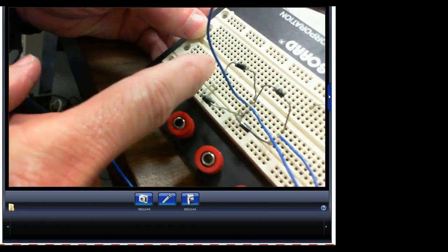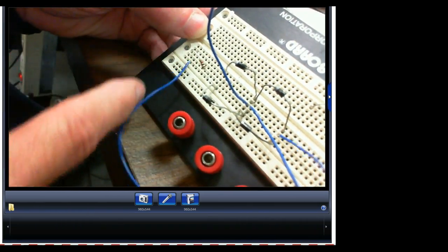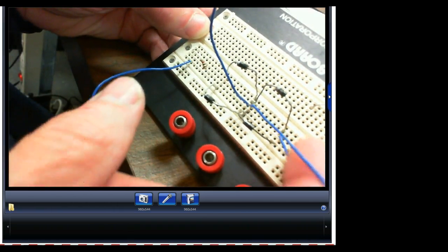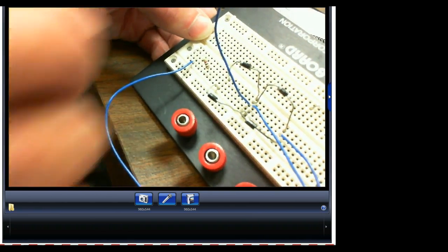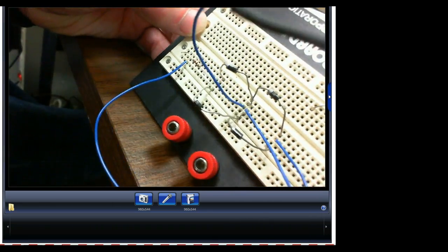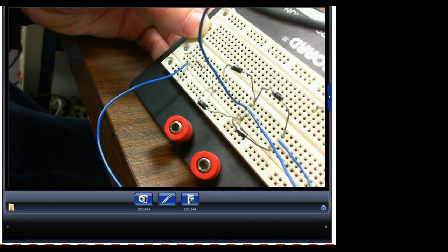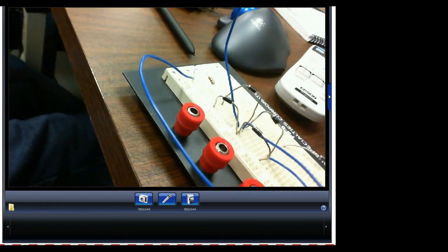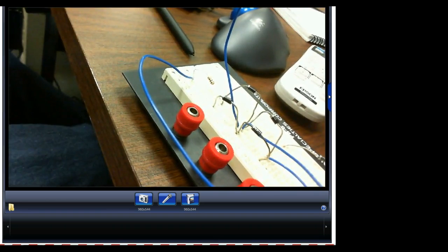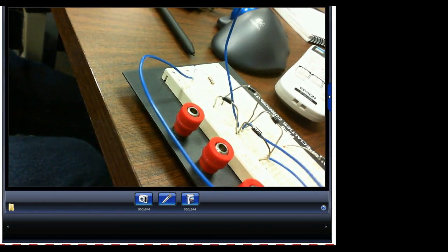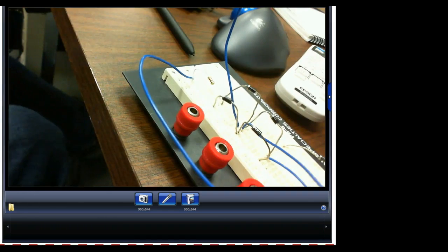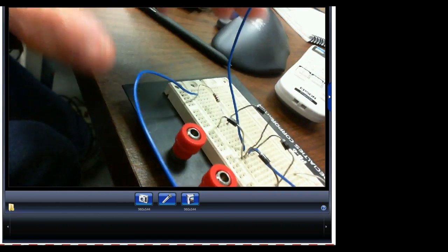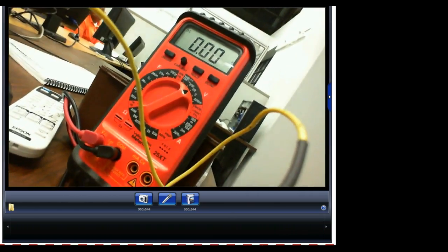So that puts this part of the resistors positive. Then I had to put a wire to come around to the other side. There's my negative. So there's my circuit. Even though they look like they're in parallel, they're not, right? You understand? A lot of people see things side to side and say they're in parallel, and they don't look to see if the ends connect together. The top and the bottom have to connect together to be parallel, right? Okay, so there's our circuit.